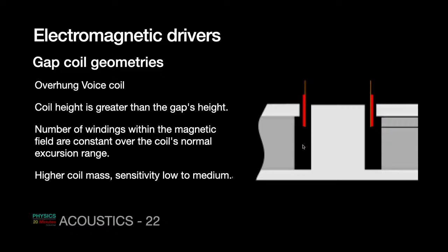But what happens if the vibrations are huge? Suppose this coil goes out so that it is only half inside the gap. If the vibrations are huge, the length will reduce in every vibration, and therefore the force acting on it will decrease drastically, and some sort of infidelity or non-linearity comes if the coil exceeds its operational limits. So this is how this coil is affecting the quality of voice. The non-linearities are not as strong as they will be in the other case.